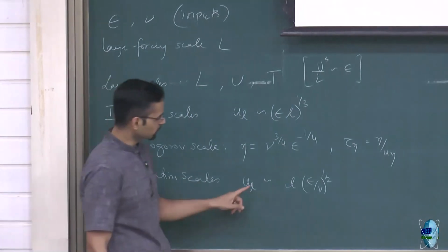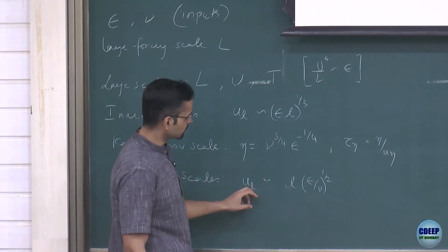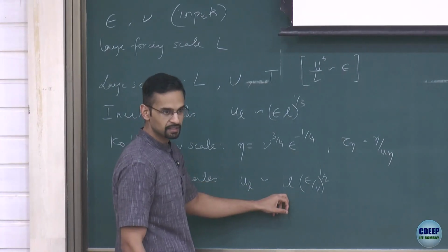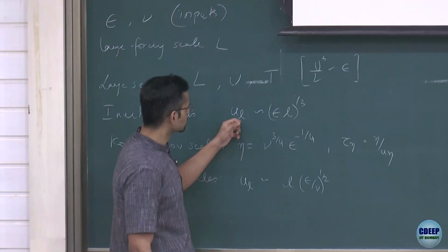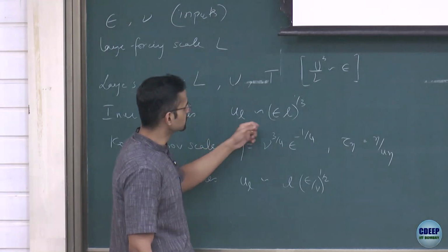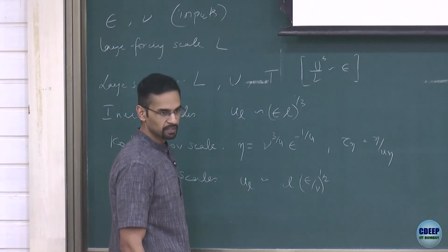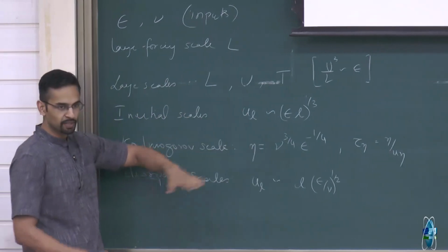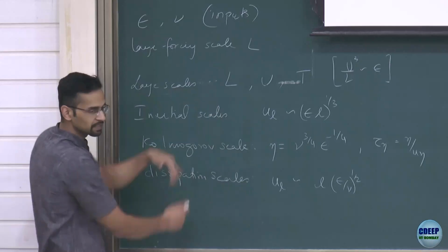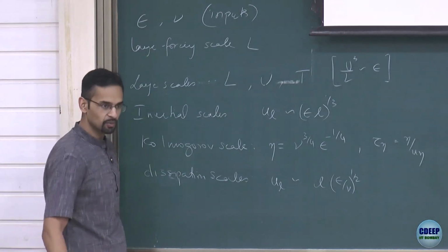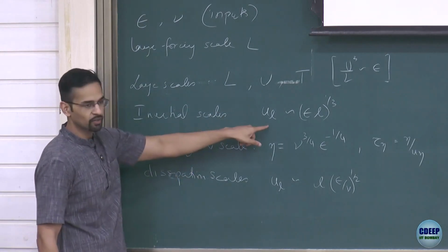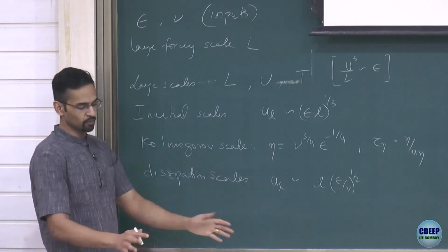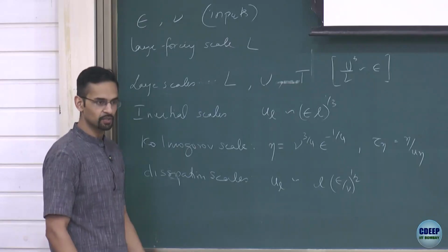Okay, so here this flow is smooth in the sense that the gradient of velocity goes linearly with L, right? Or the gradient is something constant, right? Whereas at these inertial range scales, it goes like L to the 1/3. So that's what I said, the flow is rough. If I filter out the field and only keep these inertial ranges and remove the dissipation, and if I try to calculate a derivative, you'll see it will blow up. So if I am at a certain range, the flow will look as if it has discontinuities.